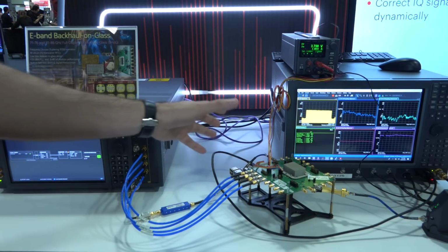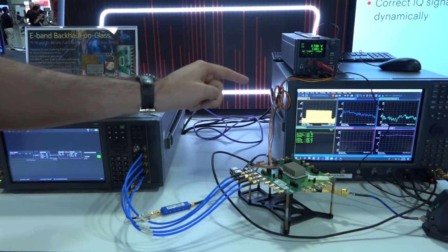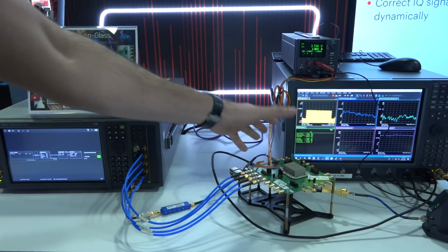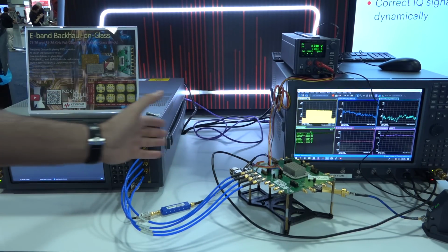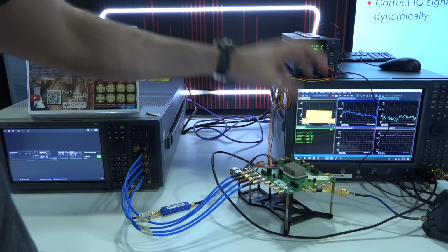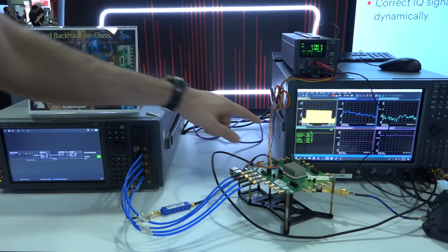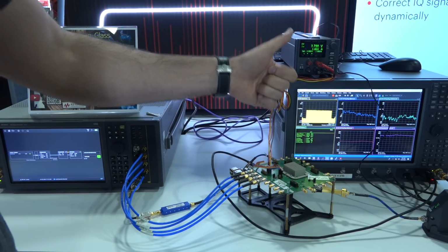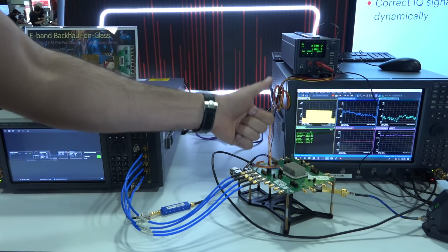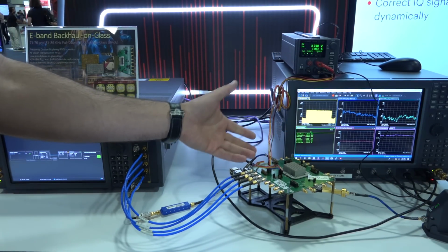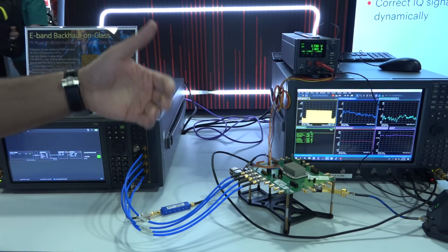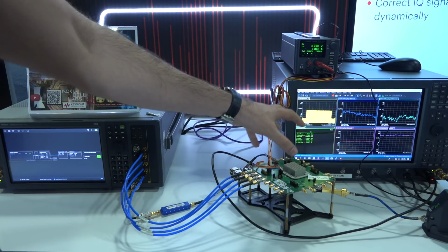So what this setup allows you to do is to calibrate all the IQ impairments and all the phase and offsets between IQ on any transmitter that you have by going through all the frequencies ahead of time, and then pre-correcting that waveform and feeding it back to your signal. So this has 2 advantages. First of all, it allows you to measure constellations which may have had very poor EVM due to IQ imbalance only and image rejection problems, but it also allows you to extract the correction data separately so you know exactly what your circuit was doing.